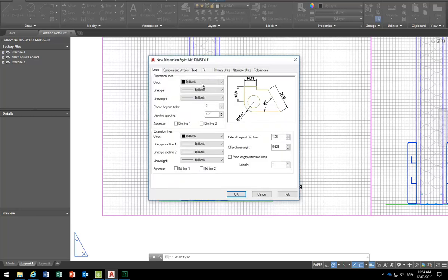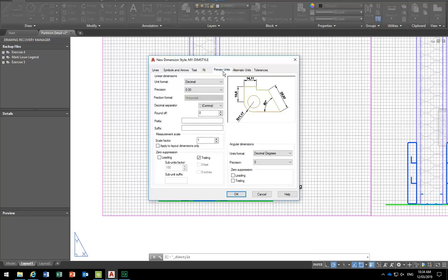Whatever, the name doesn't really matter because you only need one. So the way I do it, you only need to make one dimension style for everything you ever do in AutoCAD. Because I know last year you would have been shown to make several dimension styles, for every different scale. But then for each different scale, you would have needed a different one, the way you were doing it. When you needed to change scale, you would have needed new styles. Yeah, you must have.